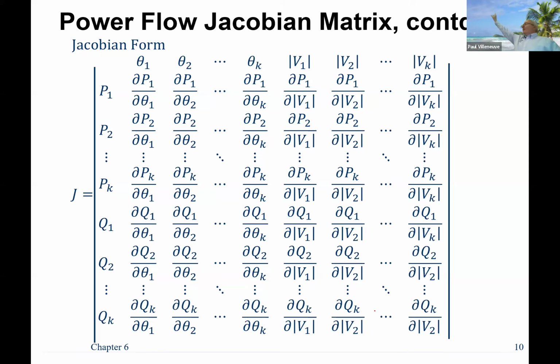Here's the important thing. Be careful not to swap theta 1 and theta 2. You want to do everything in order, because if you start swapping where things go, your results are going to get really heinous. And for those of you who are with me in lab, one person had their results not converging because they didn't have a minus sign in their Jacobian. So one sign change will completely screw up your result. So it's very important to make sure everything goes in the right position.